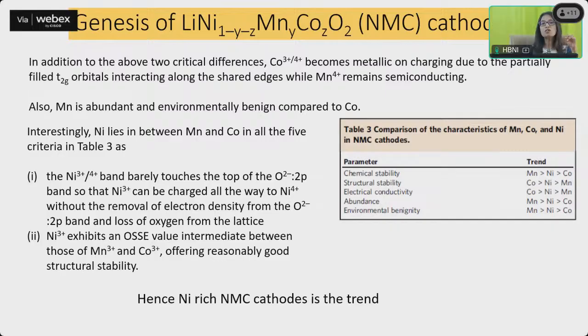What is paramount is, see here, basically your end will show your means. At the end, what you need is something which should give you a higher energy density and very high cyclability. You have to consider some important factors for a battery material. One is energy density, the other is cost, the other is the availability of the materials. But the paramount factors are your energy density and the cyclability. That is very important. If you have a very good material, but it is cycling only for maybe 50 cycles or 100 cycles, that is definitely not a good rechargeable battery. So you have to go at least beyond 5,000 cycles. Then only will we consider that this battery is good.